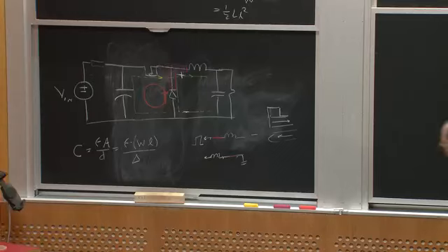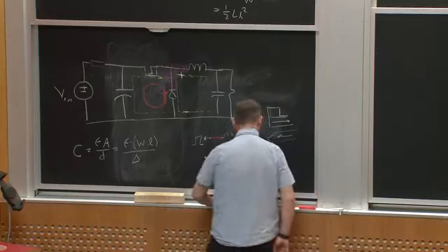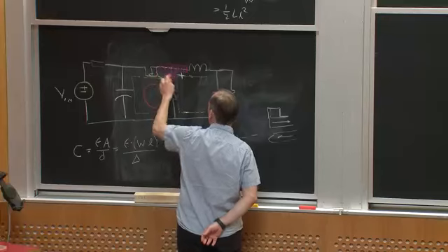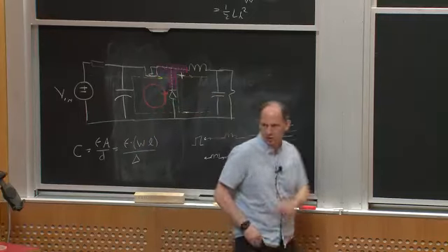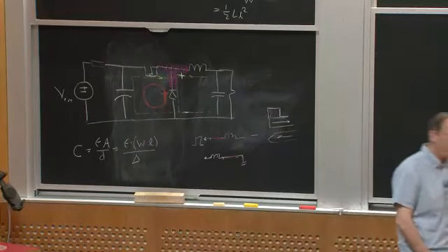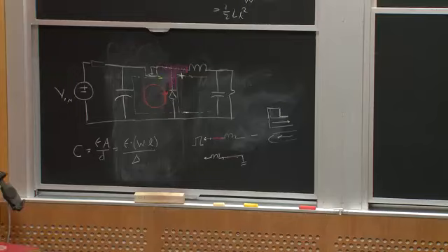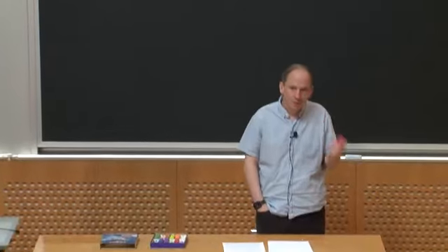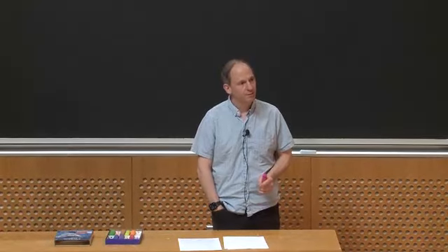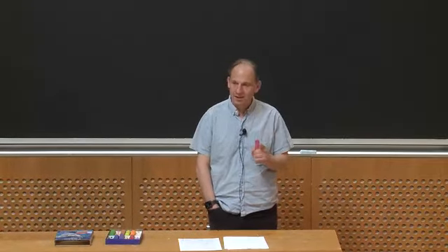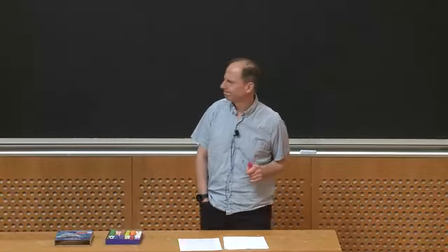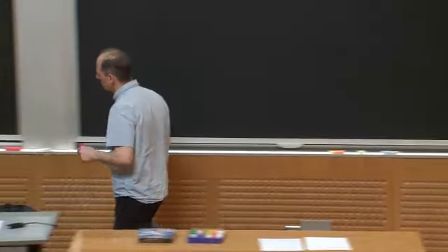Let's talk a little bit more about this switching node here, okay? One thing it does, which we saw in the demo, is it'll cause a bunch of ringing because you have excess capacitance at this node that you don't like. But there are other capacitances on that node, like the device capacitance and so forth. But what really often hurts you is the capacitance of that node not to ground, but to other stuff in your circuit.